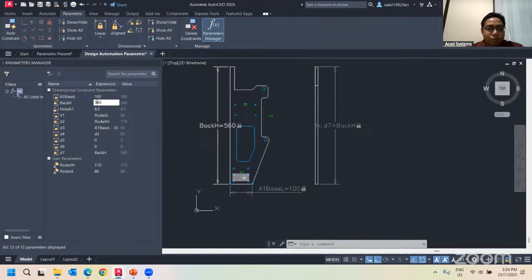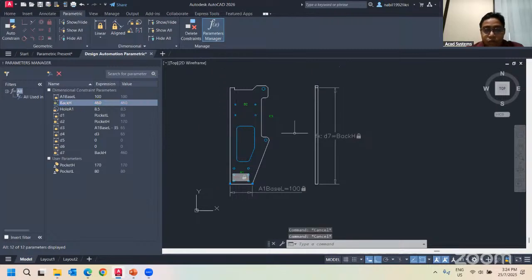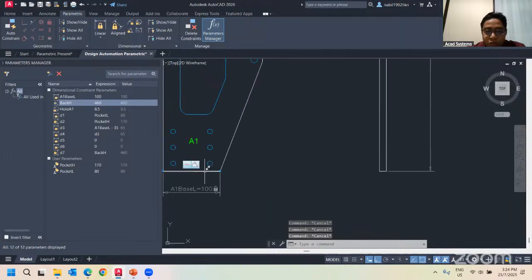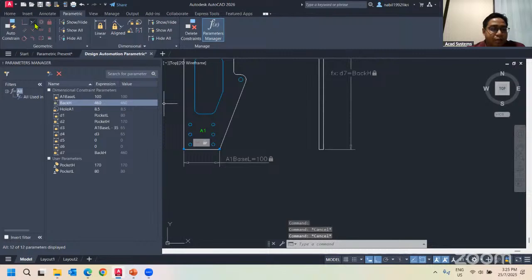But sometimes when you do that, it could be that this line ends up in the opposite direction. Maybe this one I pull up, this one pulls down. In that case, I can add some more geometric constraints to make sure that the base here is aligned with this. I can add something like a collinear constraint so that it will be aligned.